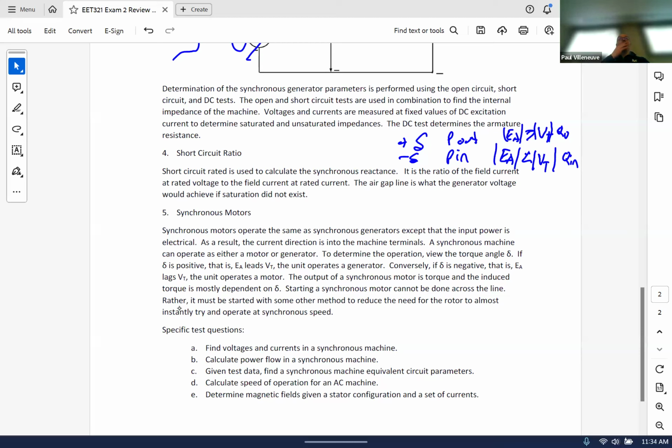It's like somehow if you had a reciprocating engine and you wanted it to actually pump, maybe you could go in both directions where you could either compress fuel or you could decompress fuel. So maybe like a heat pump for your house, that can work in either direction. So maybe something like that, but you don't see a lot of applications like that. Most of the applications, you'll see a motor that gets it up to speed. And like I said, in some cases, you'll actually run the generator with a variable frequency drive to do that, but those are pretty expensive. Whereas a small motor, it depends on the size of the motor, but a 1,000 horsepower motor might cost you 12 grand, 13 grand. You need some complicated mechanical systems to couple those two, but you can make those work.